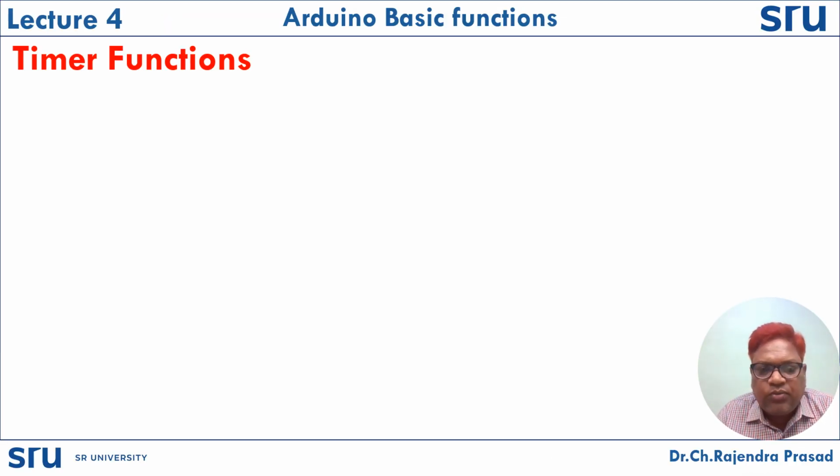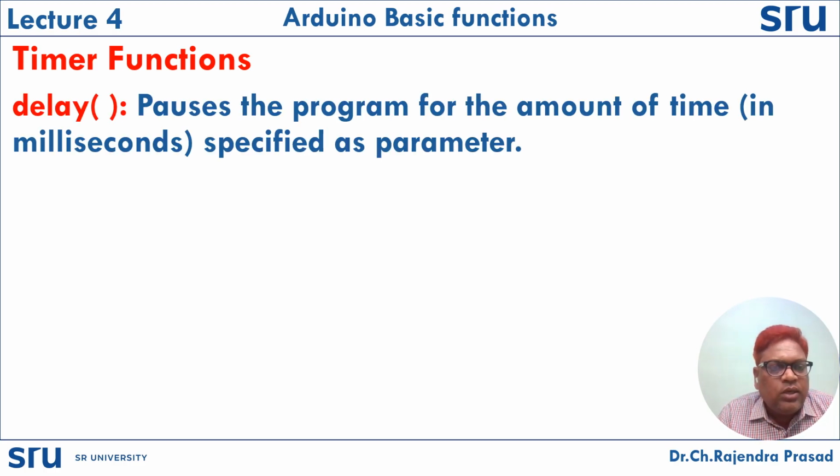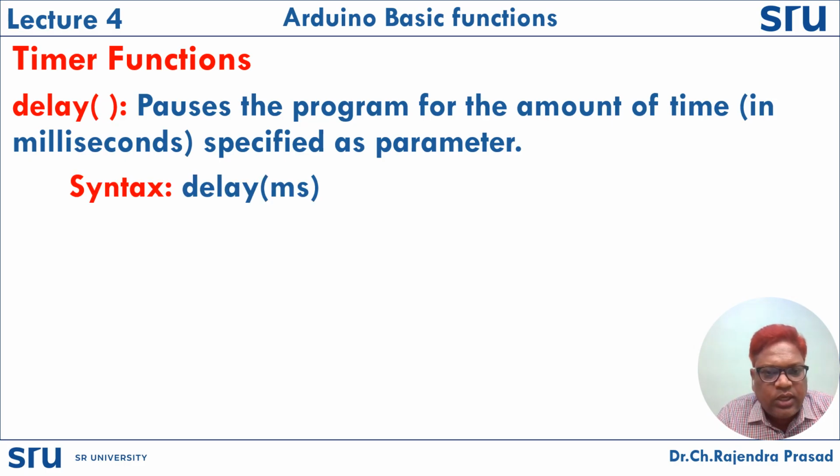Then coming to timer functions, in some applications we need to provide delays in between the actions. So in order to provide this, the Arduino software itself provides two delay functions. One is delay. This function pauses the program for the amount of time specified as a parameter. The time should be in milliseconds. So let us see one example here, the syntax for this one, delay milliseconds.